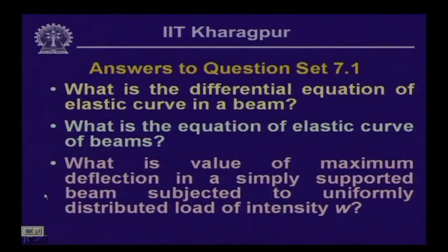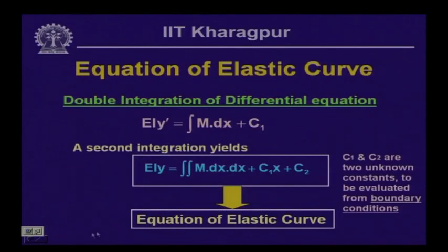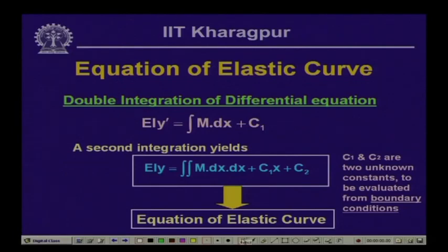Now, the second question posed was: what is the equation of elastic curve? The first question was the differential equation of the elastic curve, and the second question is the equation of the elastic curve of beams. Subsequently, once we get the differential equation for the beam, which is E I d2y dx2 equals the moment, if we integrate it